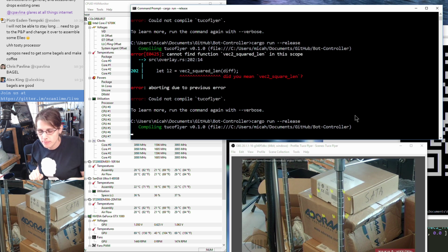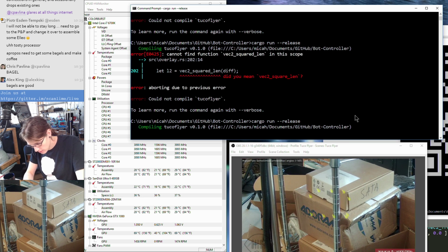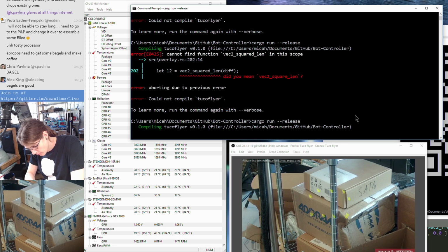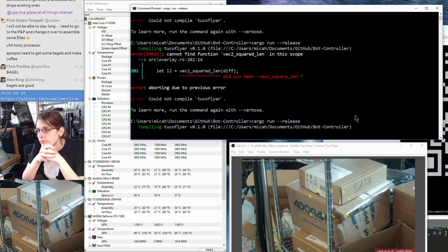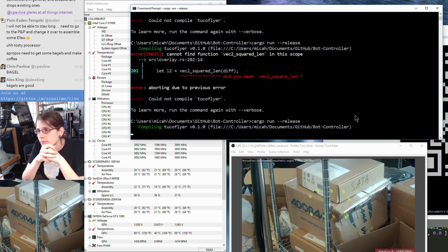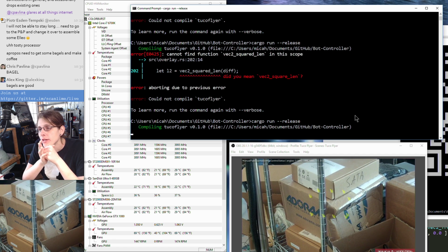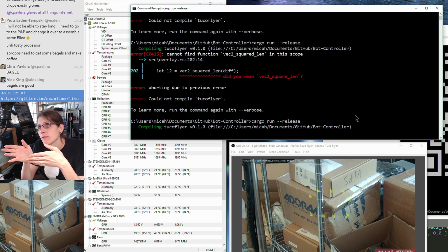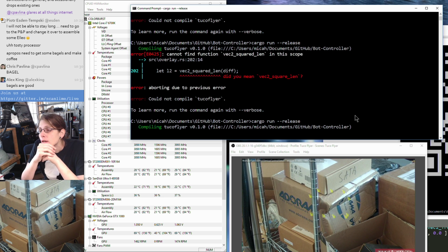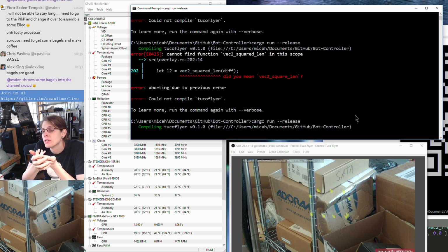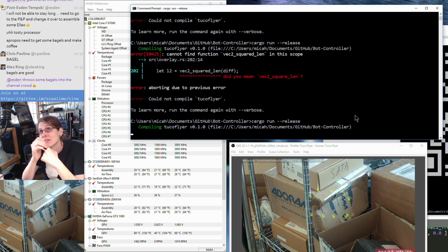Yeah, that might just be a matter of tuning, actually, so that might be worth looking into. See, this is just the gyro having a static velocity vector, which might not have been 0. It might have been a small non-zero number. So it's some combination of a small non-zero velocity vector probably, plus the gyro drift, and it just eventually goes off in some direction.